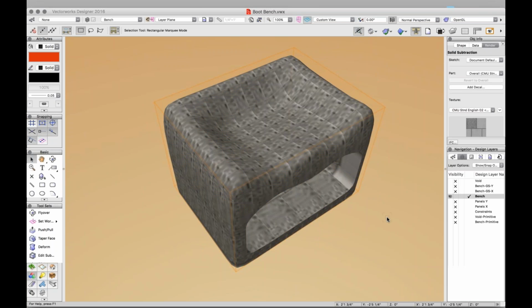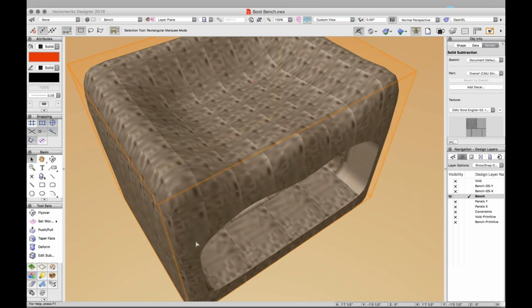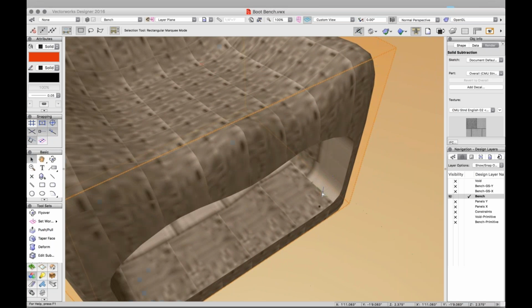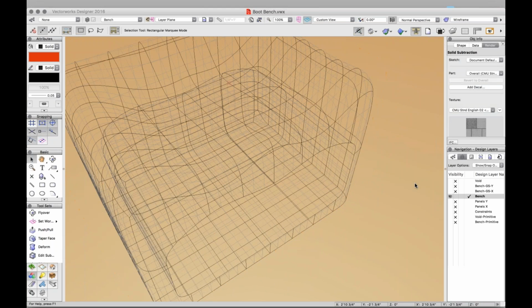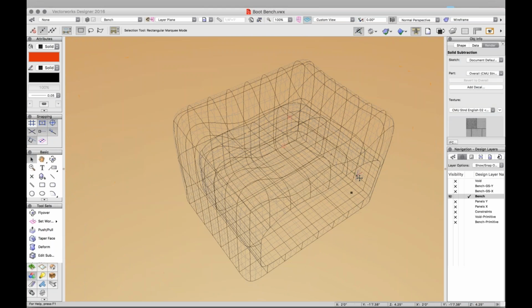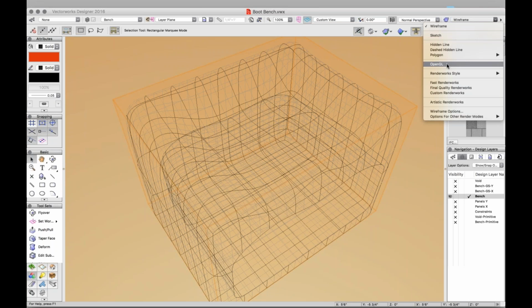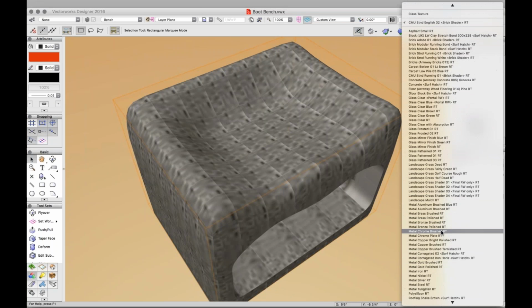Now I don't know exactly what I would want to assign to it, but you'll notice here that I've assigned a CMU texture. Something to pay attention to is the way these primitives are created, your grid is a little bit stretched in some circumstances. If I go to a wireframe view of this object, we'll see that not all faces are equal. Therefore, on some surfaces, it does stretch that texture around, so maybe not appropriate for more rectilinear textures. But if I go back to OpenGL and switch to something, let's say, for example, we could give it a grass shader.